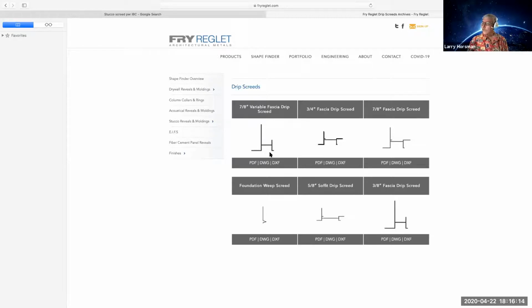These are supposedly built for, see, this is a problem here, where you have a soffit. A lot of times if they just run the stucco down and they don't provide a curve for a drip or some piece of molding there, the water will run down the vertical face and then roll back on the horizontal face and you'll wind up with a bunch of staining near the edge.